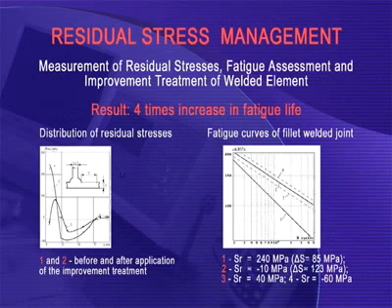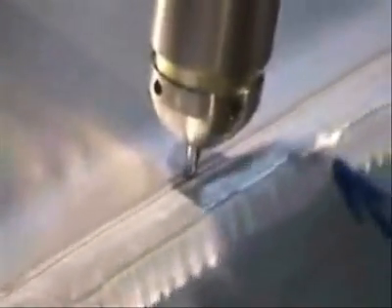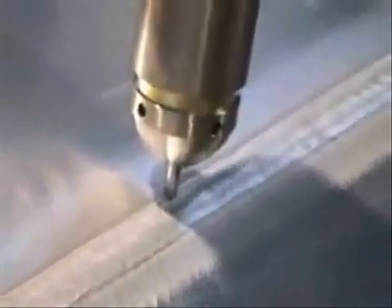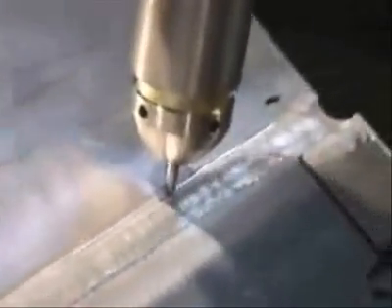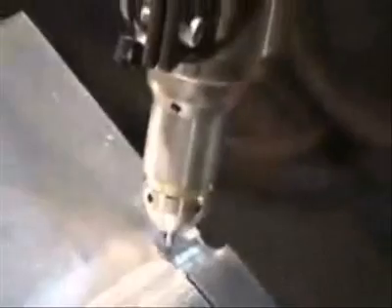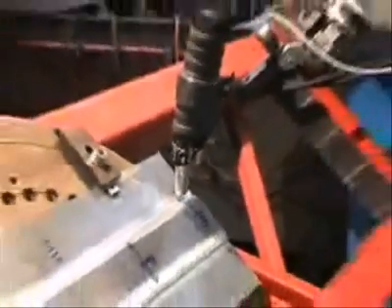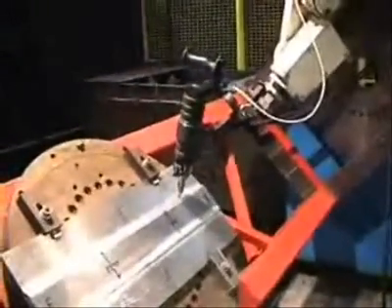In addition, the developed expert system can be used for calculating the effect of measured residual stresses on the fatigue life of structural elements based on the mechanical properties of the material, the type of welded elements, and cyclic loading parameters. The expert system for fatigue assessment and optimization of welded elements and structures was developed to find the optimum way to improve the fatigue life of welded elements without increasing its metal consumption.